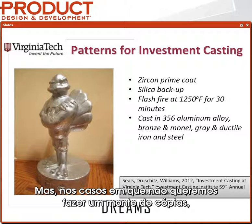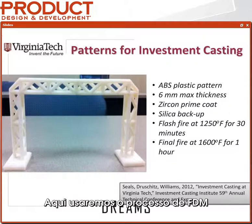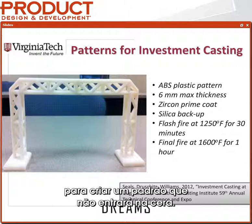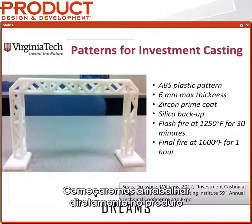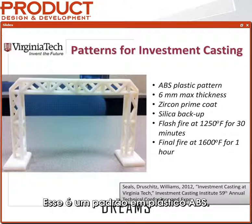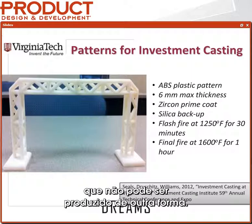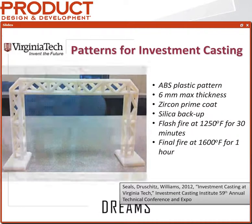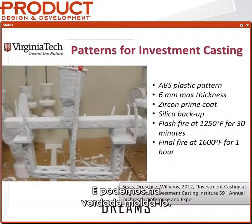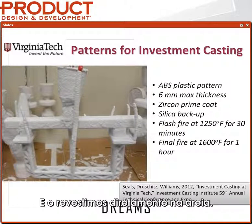But in cases where we don't want to make lots and lots of copies, we look to a different way of making a pattern. Here we're going to the FDM process to make a pattern where we don't go to wax. We actually work straight from the product that came out of the printer. So this is an ABS plastic pattern. This is a truss structure, a sort of cellular material, something that can't be made by any other means. And we take that ABS pattern and we directly coat it in sand.